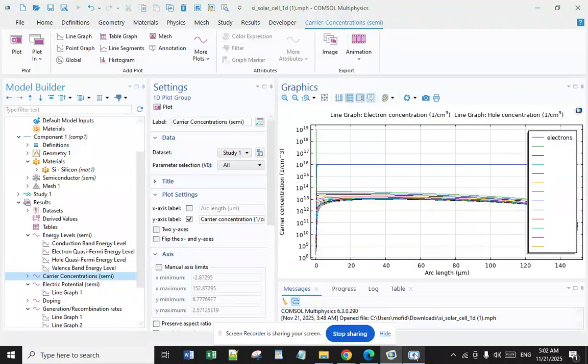The next step is meshing. Generate a mesh of the geometry, with specific attention to areas such as the contacts. You can use mesh control to create a finer mesh for more accurate results, while ignoring certain boundaries for physics settings. Step 2 is to add the semiconductor material.